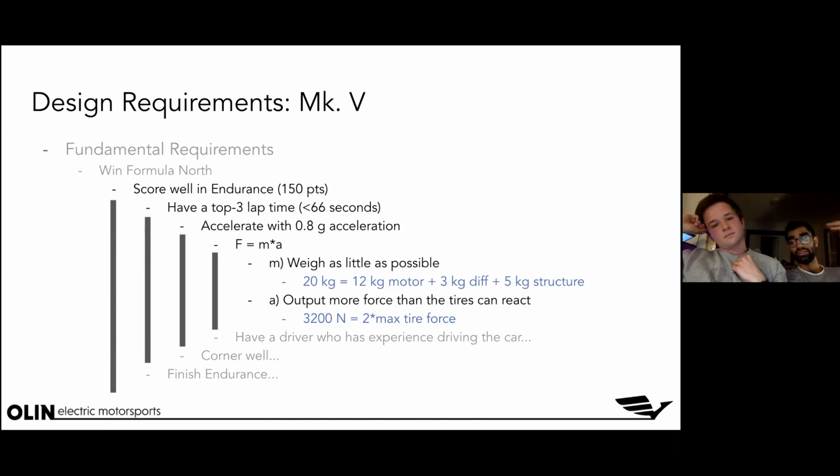And you're slowly going to refine those numbers as you look into each detailed part and say, here's what we had last year. Here's how much room there is for improvement. If this is our new weight target, here's how the accumulator energy is going to change. If the accumulator energy is changing, now that system's getting lighter. So now our force requirements are different. And you're kind of sifting down iteration by iteration with all the sub-teams together as opposed to each sub-team individually.